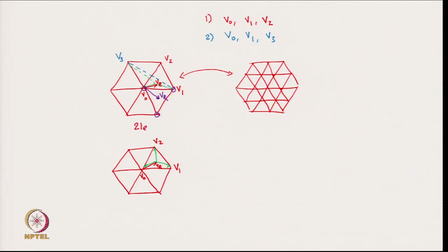So, this is the 2-level space vector diagram, this is the 3-level space vector diagram, which we will see later how this diagram comes. The space vectors are becoming denser and denser. If you go to a 5-level converter, it will become even more dense.